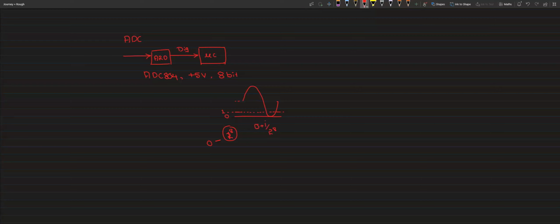Okay, so if it is like plus 5 to minus 5 volts, so every step, like total, we have 10 voltage range, right? So that resolution we say. Okay, so since we have the 2 power 8 bit resolution, maximum voltage, like if it is 0 to 5 volt, plus 5 volt divided by 2 power 8 volt. This is the minimum voltage what I can represent in analog.